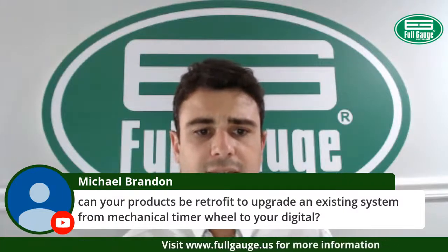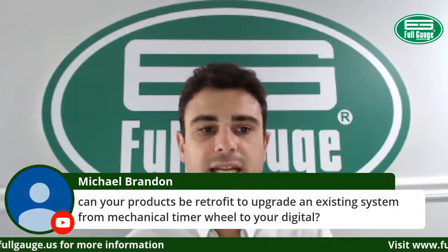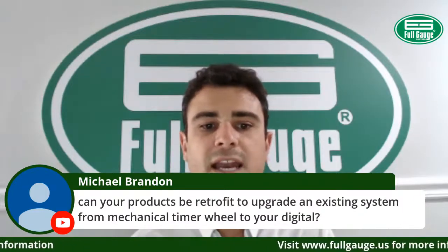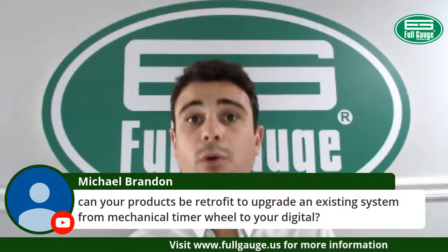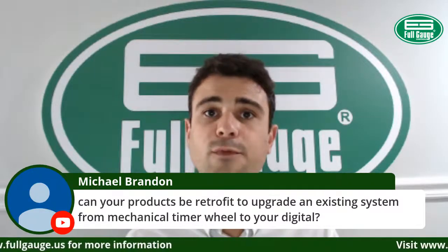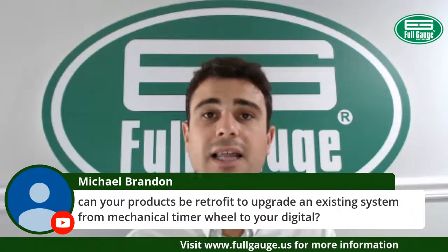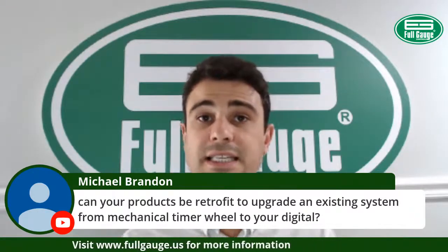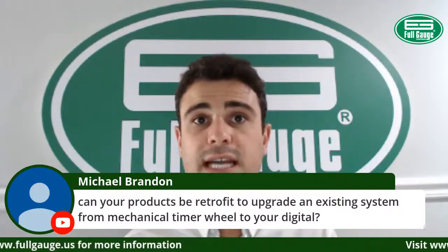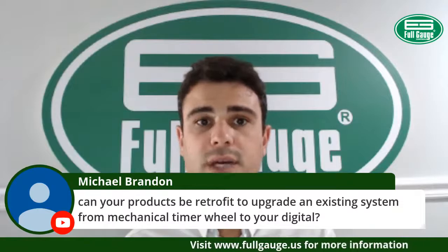Michael is asking if the products can be retrofitted to upgrade an existing system from mechanical timer to digital. Yes. Our digital controllers, for example the TC900, will allow you to replace the thermostat, defrost timer, fan termination switch, and the defrost termination switch.